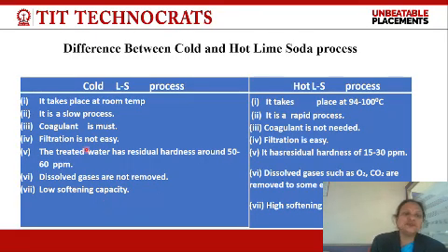There are some differences we should remember. The cold lime soda process is performed at room temperature and the hot lime soda process at hot conditions, about 90 plus temperature. Cold lime soda process is a slow process and hot lime soda process is a rapid process. Coagulant is a must, compulsory, in the cold lime soda process, and in the hot lime soda process coagulant is not required.